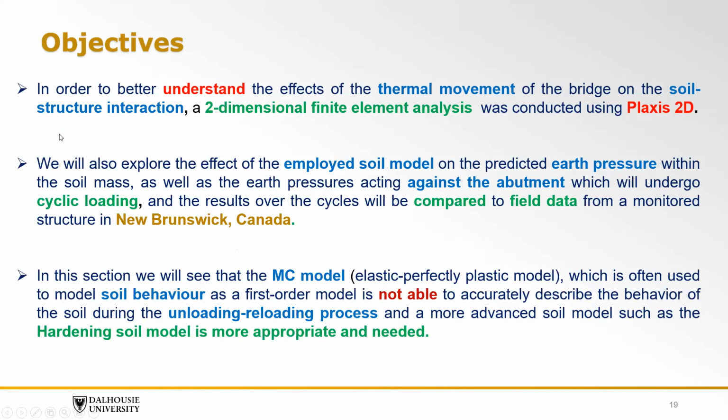The objective of this part of the lecture will be to understand the effect of the thermal movement of the bridge on the soil structure interaction. We're going to utilize a two-dimensional finite element analysis. We will also explore the effect of the employed soil model, to see its effect on the prediction of the earth pressure within the soil mass, as well as the earth pressure acting against the abutment, which undergoes cyclic loading.